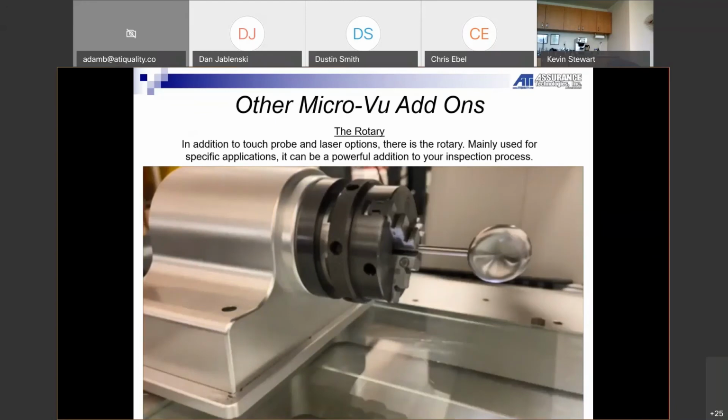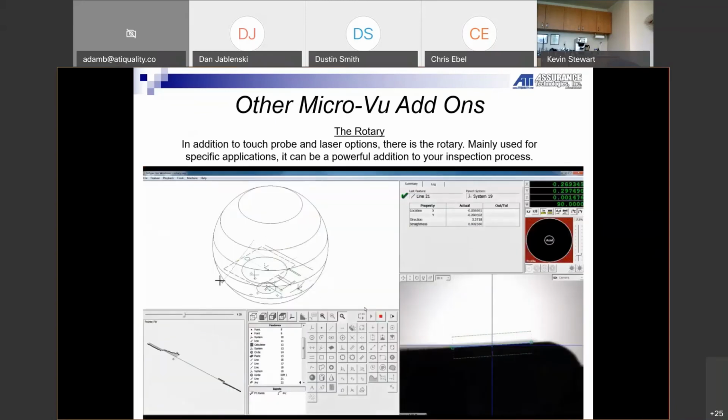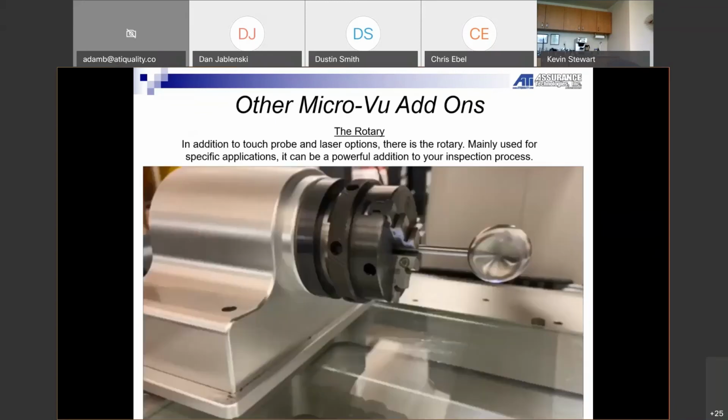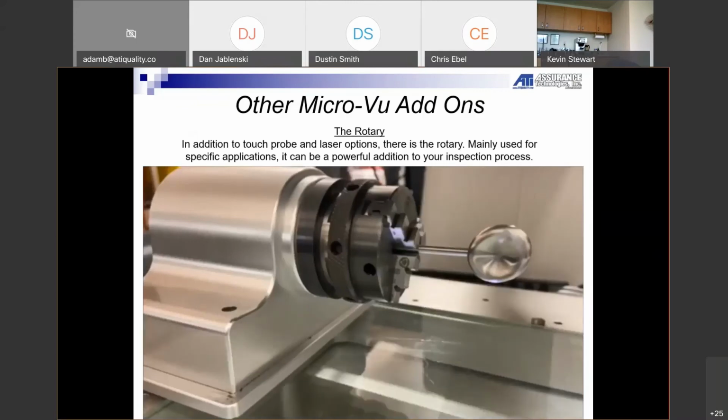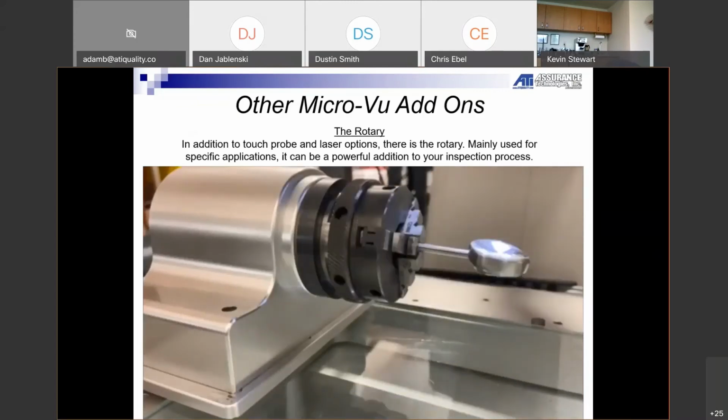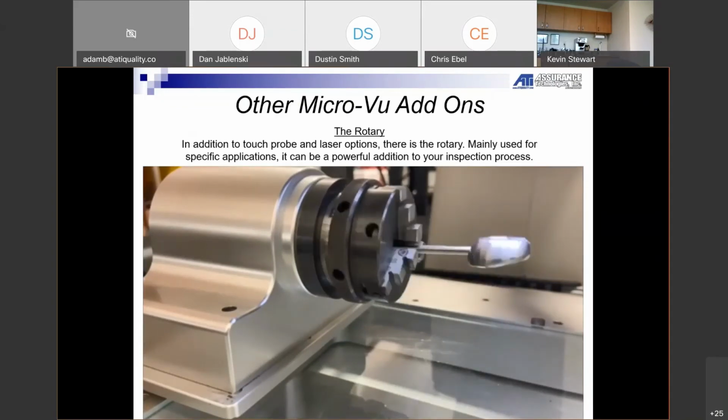And then right there, there's a threaded hole on the side and that radius there that I needed to get. And so I'm able to, in one program, flip the part multiple times and get all of my measurements that I need on there. And the last true position that I needed to get was the center of this sphere. You could kind of see that curved surface on that part.